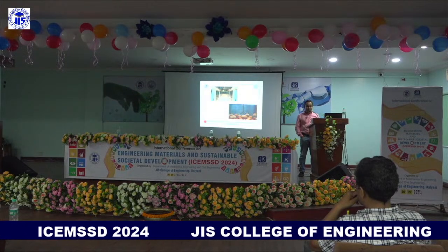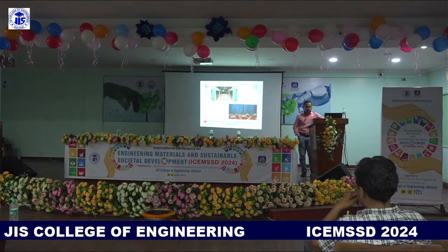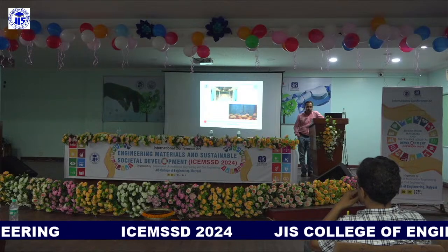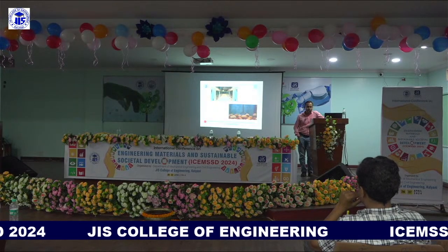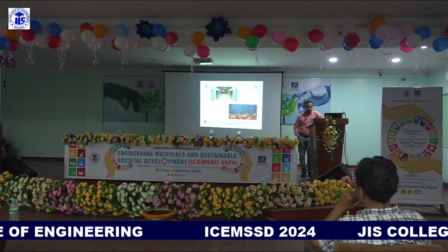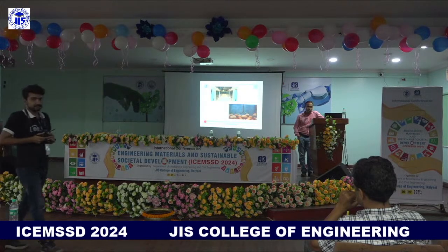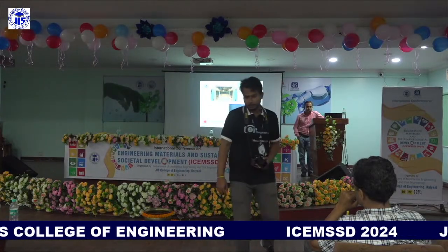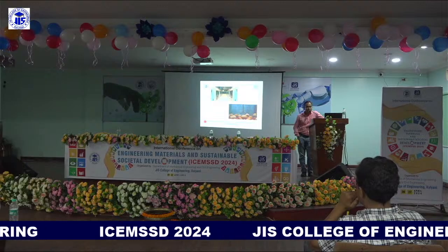The Froude number is equal to V by square root of gH. That means if we know the approximate velocity in a river and the depth in the river, then from there we get an idea of the Froude number, and we can use the same Froude number in the laboratory by changing the depth as well as the velocity, because we will not be able to change the value of g.